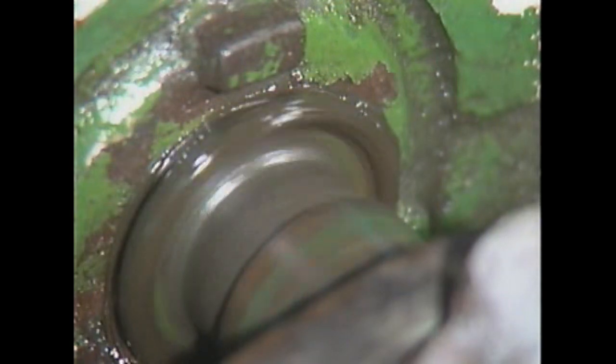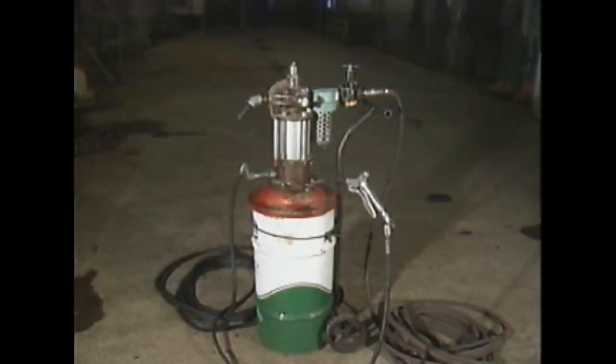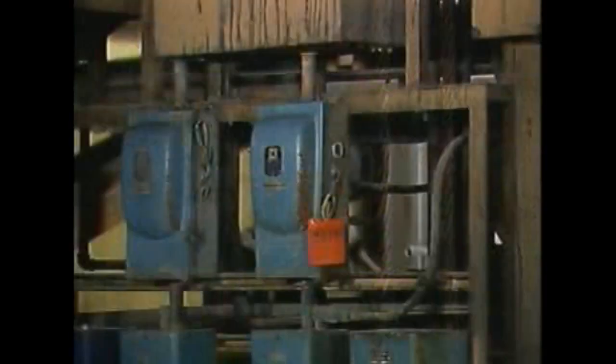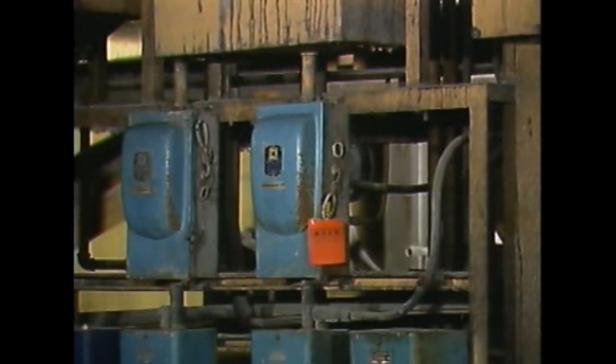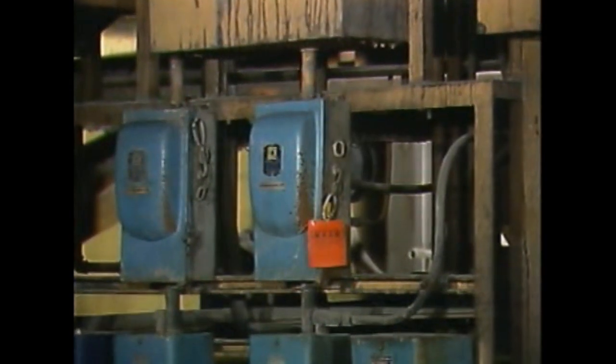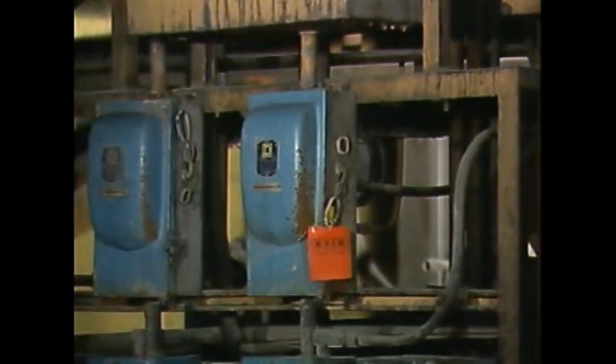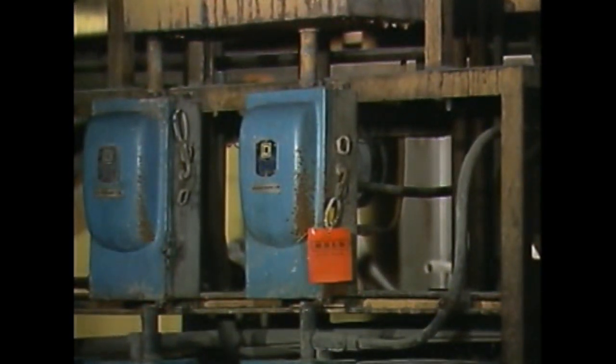Another reason for using grease is that grease may be required to assure that contaminants are prevented from getting between lubricating surfaces. In this part, we'll look at some typical examples of how to apply grease for proper lubrication of industrial equipment. Sometimes workers apply grease manually with a brush, clean cloth, or their gloved hands. The workers must use the required personal protective gear and make sure that the equipment is turned off, locked out, and tagged before they apply the grease.